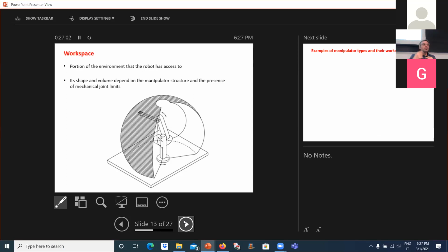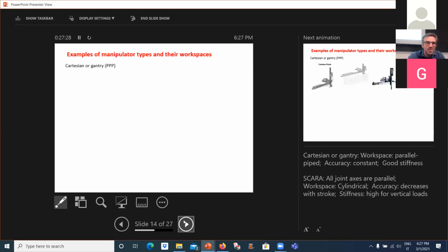So you could also think about a link that is moving endlessly with a motor. But even there, if you have some sensors at the end, you have some wire that winds up and then you cannot move. In our new quadruped robot, we can do 3 turns and then the wire gets squeezed. So all of them in general have kinematic limits. And so that shapes the workspace.